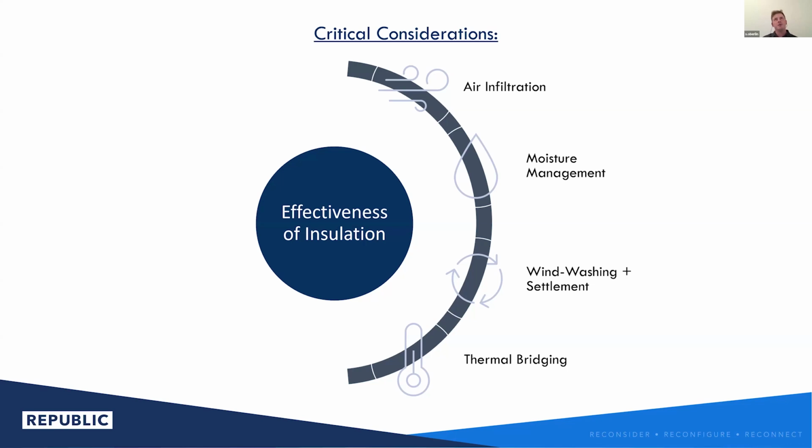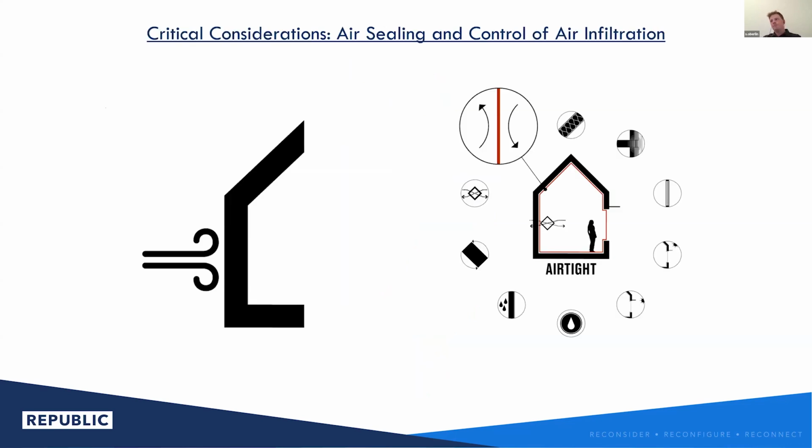Since these buildings were tuned to a specific net annual energy usage, we made sure that we were fairly conservative in our effective R value calculations, doing quantitative takeoffs of the blocking and strapping in the walls and understanding how much thermal bridging is really going to be present in the built condition. We made sure our energy models were set up so that we weren't going to get a number in the model that was not reflective of what we were seeing in reality. So we'll want to move to questions soon.